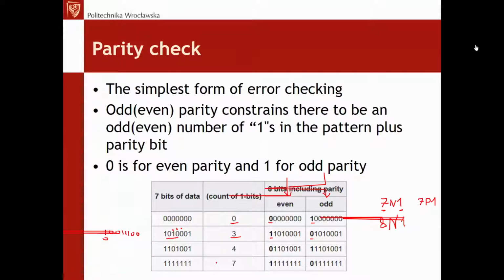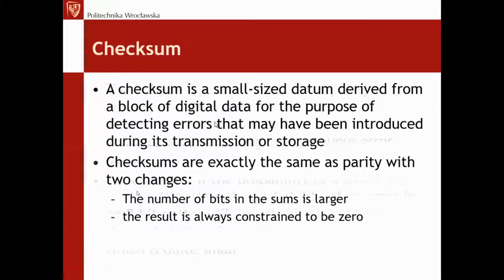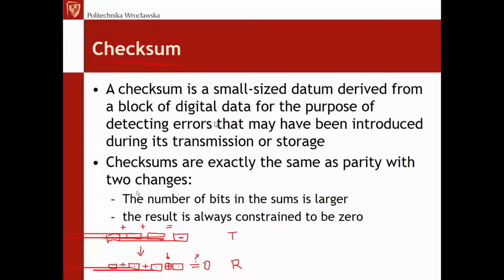So for frames consisting of, let's say, 100 bits of information, we have to count every bit in this information, which would take a huge amount of time, a couple of hundreds of cycles. And here with the checksum, it's about a couple of additions. Simple operations, usually single cycle on a microcontroller, no looping even here, although maybe a loop, of course, because we can then increase the number of input bytes or words of information, and then simple code as the final.